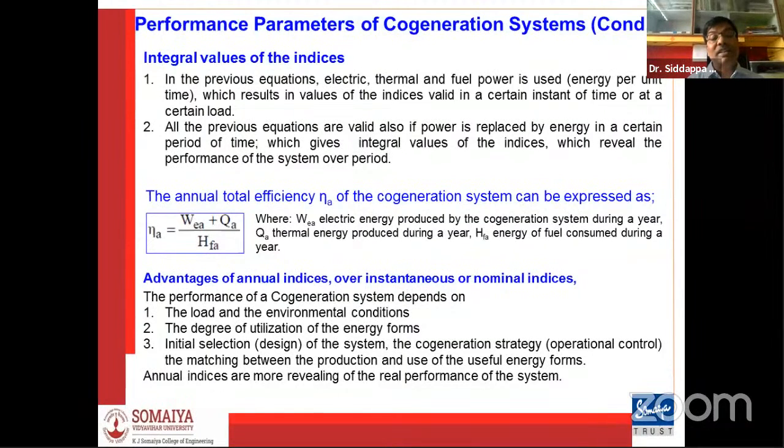But in summer conditions, I have a higher atmospheric air temperature. Fine, I'm not going to spend more fuel. But the mass of air entering the system will decrease, because the specific volume of the air at higher temperature is higher. Then the power produced reduces.